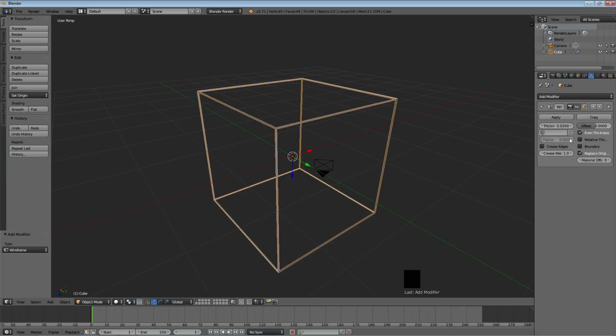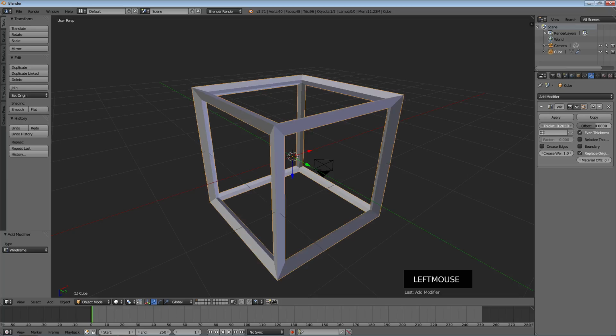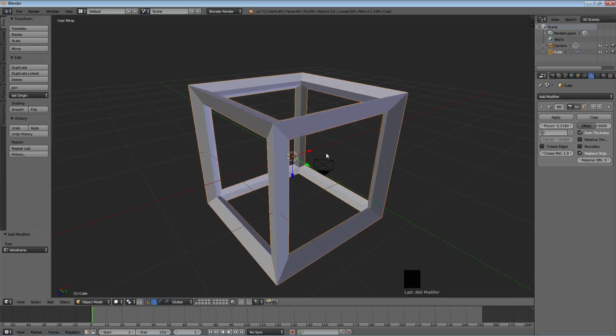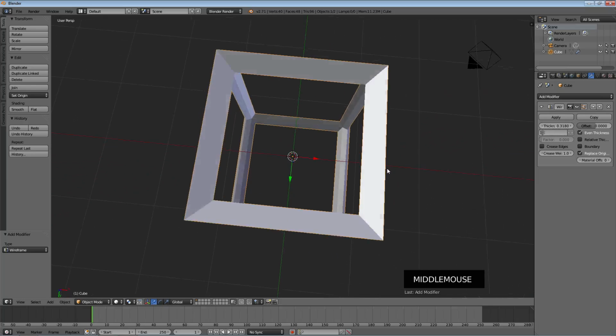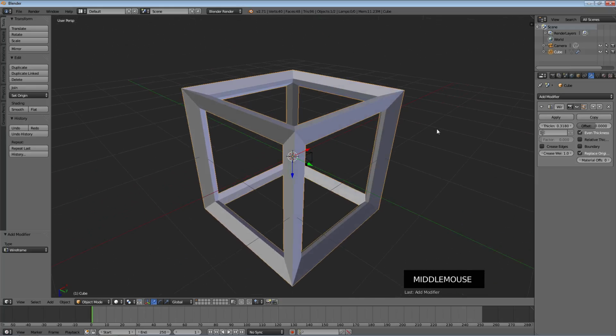You can actually copy to make a new one if you want, but look at some of these sliders. So the first slider I want to look at is this thickness factor, and this is the main one. This is the main, I guess, parameter for your modifier here. And if we click and drag on it, or you can type a number, you can see that it gets thicker and thicker as I increase thickness. It makes sense. Very simple and straightforward.